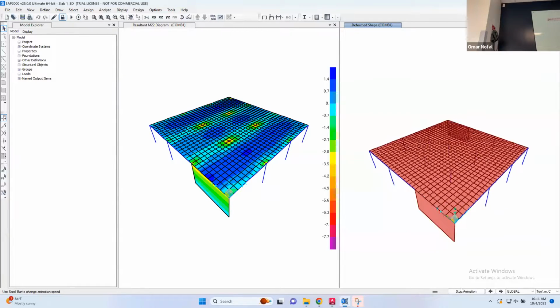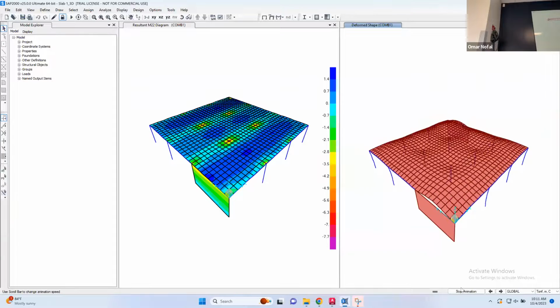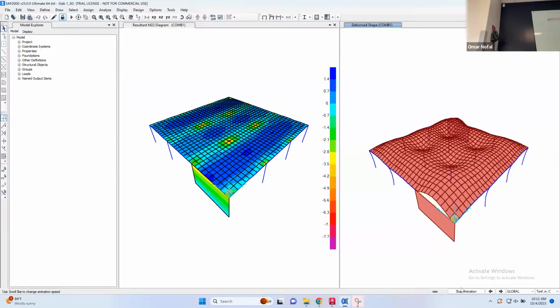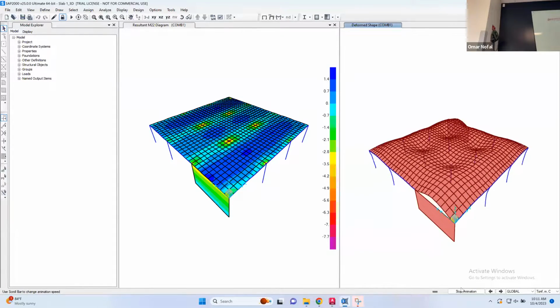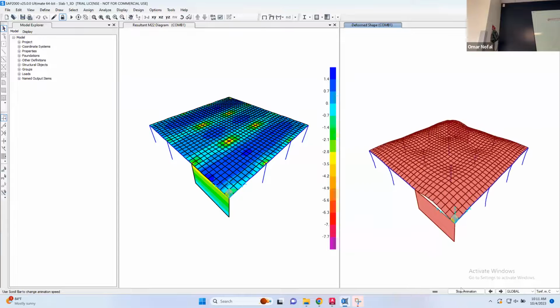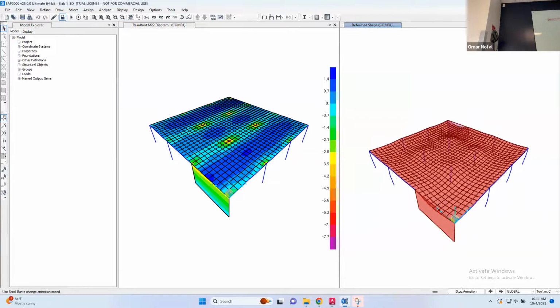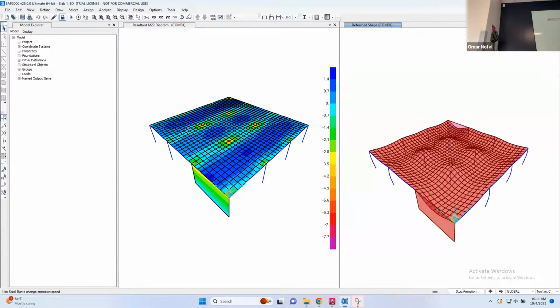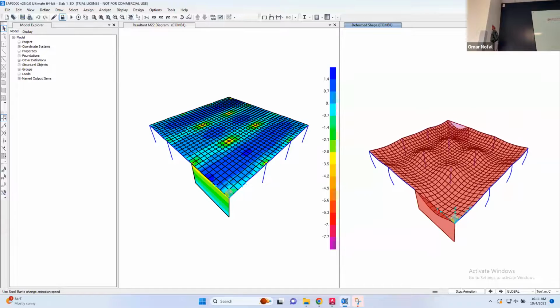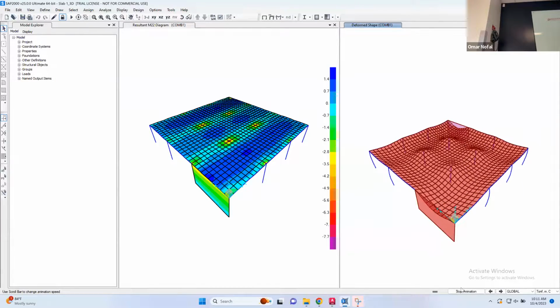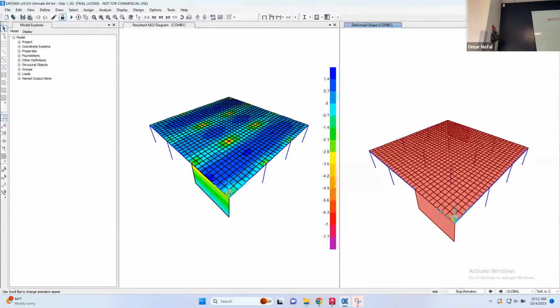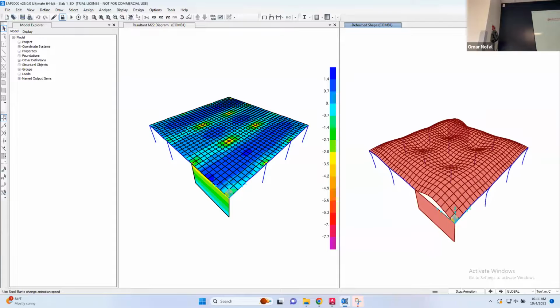What is it? The shear walls. What was happening here? They are not connected. Why? Because we talked about things a few minutes ago, right? Because SAP2000 or any finite element software connects or transfers solutions at the joints. Okay, so I have many joints here, but this element only has 2 joints, so they are not connected.